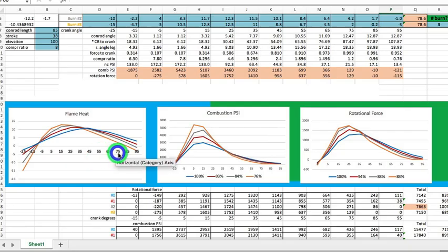Here we have 4 examples of combustion in the cylinder. From the blue, happening very slow, peaking later, and not being fully dissipated when the exhaust port opens at 95 degrees ATDC, which is an equivalent of 170 degrees duration.